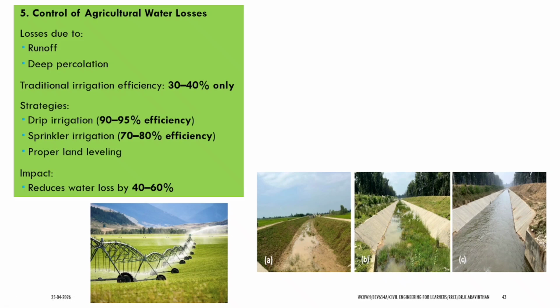Now, if you don't have this kind of canal lining, what will happen? This kind of soil erosion will happen. Slowly, when the water moves, the soil will get eroded, and the sides also will get eroded. It will increase in size day by day, and it takes all the richness and goes through, creates a clog in the water flowing path. Now, you can reduce this by making this kind of canal lining, and this reduces the water seepage into the soil.